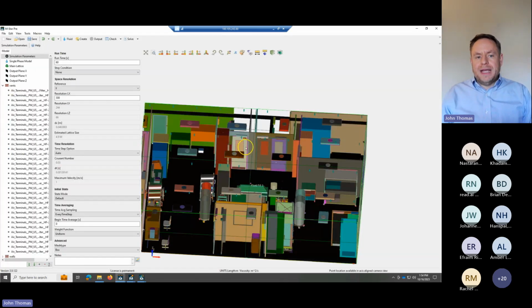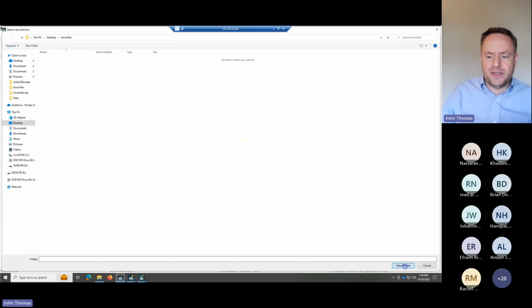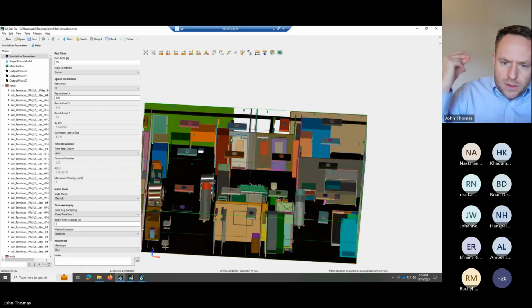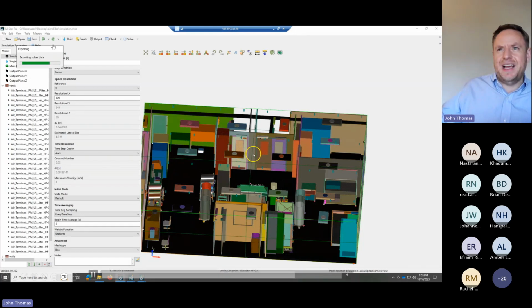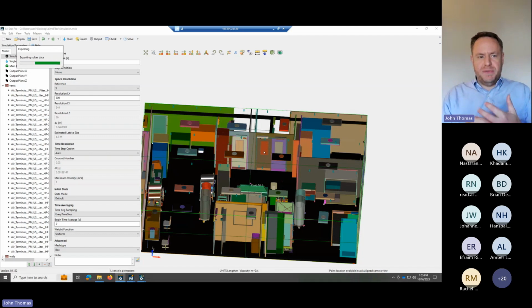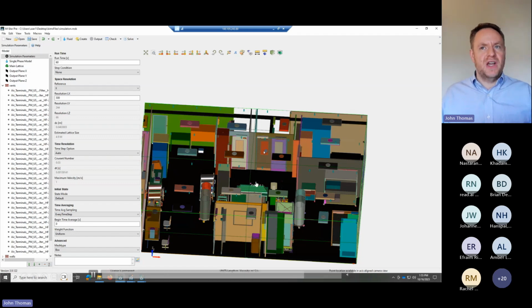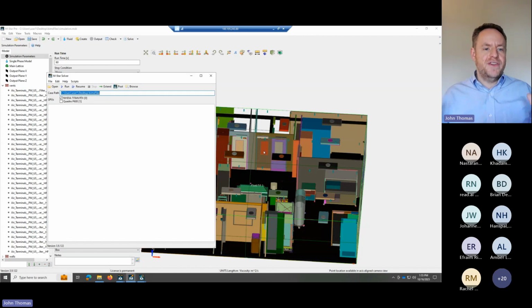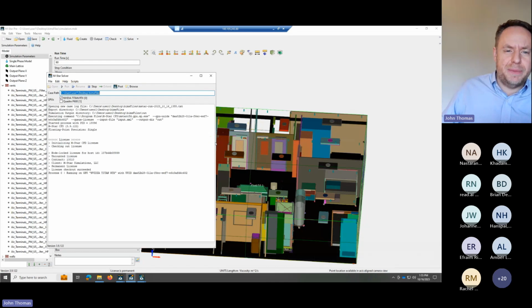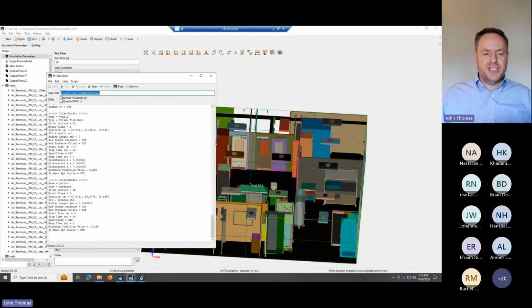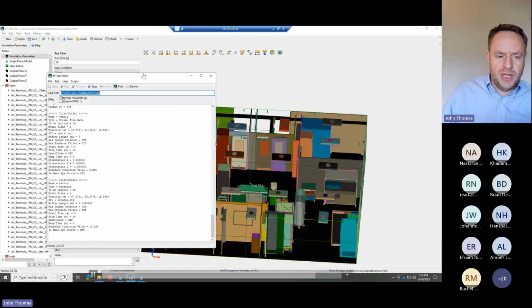And importantly, once I select this file and hit go, we're gone. I'm exporting this mesh, which takes a bit to do, of course. It's like 100 megabytes of data, so it takes a while to export all this mesh. But foundationally, once it's running, again, this movie is like 3 minutes long, and there's a point there. The fact that I've sucked in this geometry, I defined boundary conditions, albeit just 2, did whatever cleanup I needed to do, and now I'm off and running. At this point, this simulation is launched, and I'll be able to see it march through time as it finishes its final setup.